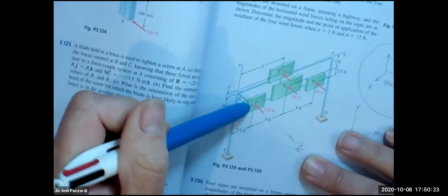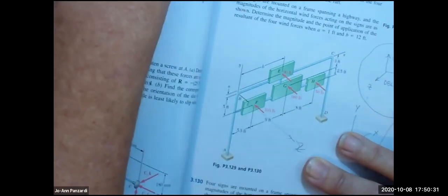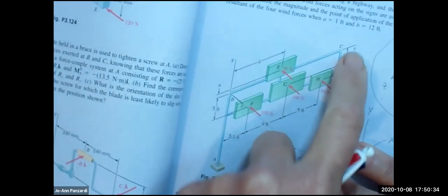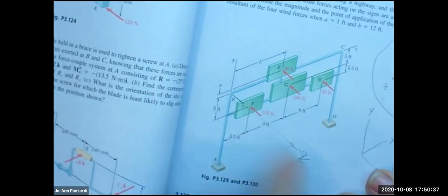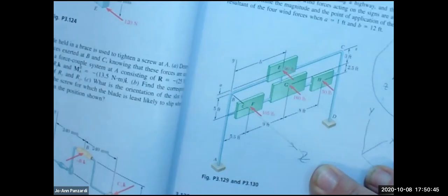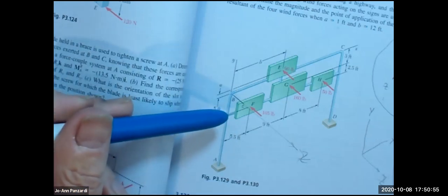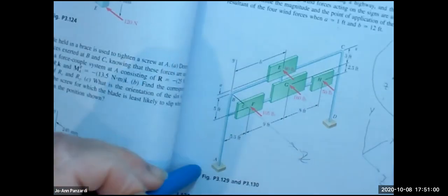So do these forces create a moment on, do you see where the axes are? This says X. This says Y. This says X and this says Y. So Z is here, I drew it. Do they create a moment about the Z? No, but they create a moment about the Y and the X. That's correct. Do they create a positive or negative moment about the Y? Positive. Correct. Fingers go in the direction of the force, palm goes towards the Y-axis.